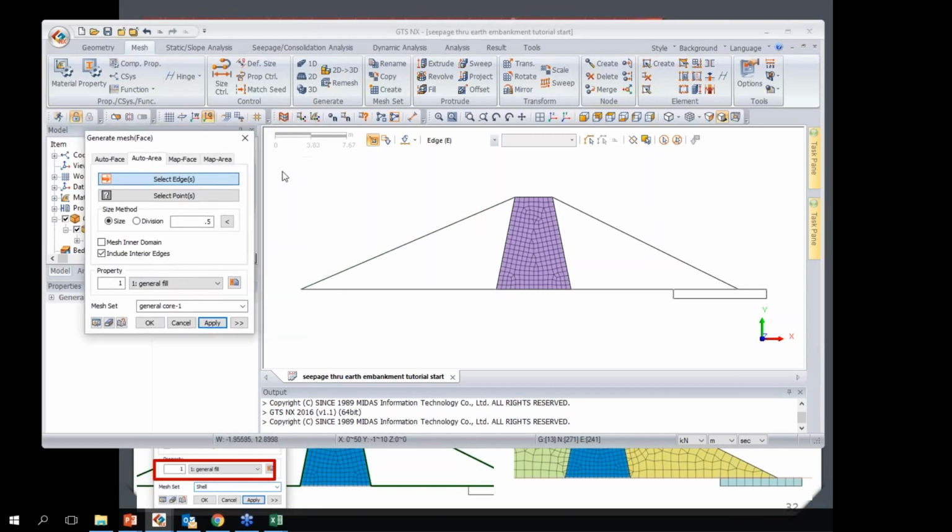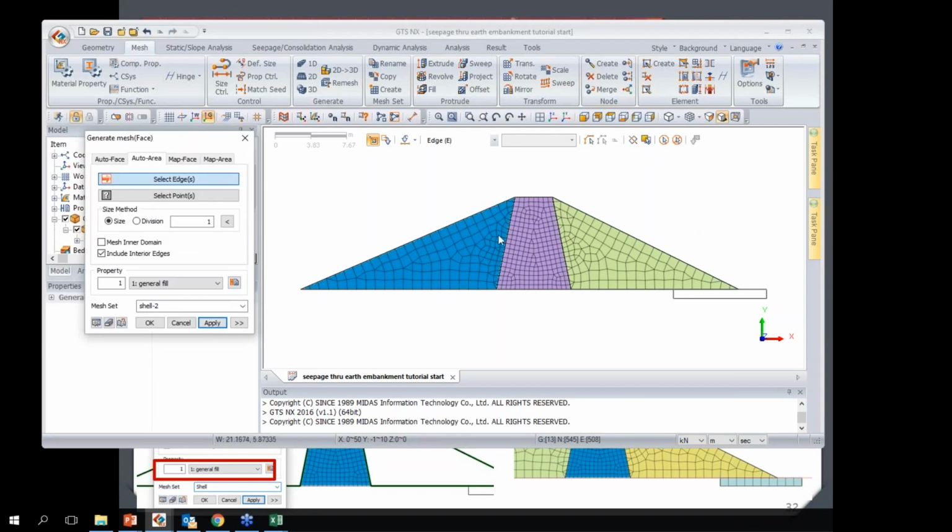And then we would have meshing the 2 shells. We would just give it a different name. And we want to give it a bigger size. We'll do 1. We see the automatic gradual change of size to match. We'll do the toe. We'll leave it as 1.